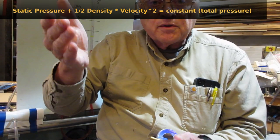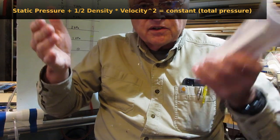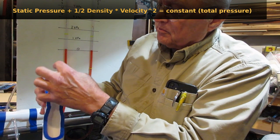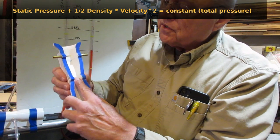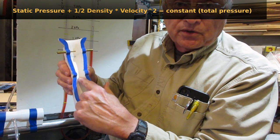Because according to Bernoulli's principle, the total pressure remains the same. The things that change are the static pressure and the velocity. So, given the same mass flow here as here, the velocity has to go up to get the mass through, right? That's just conservation of mass. And as that velocity goes up, the static pressure goes down, okay?